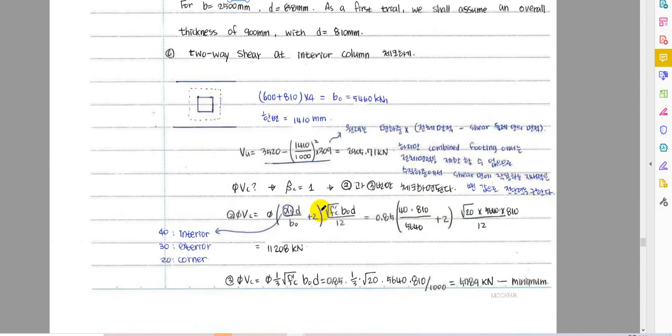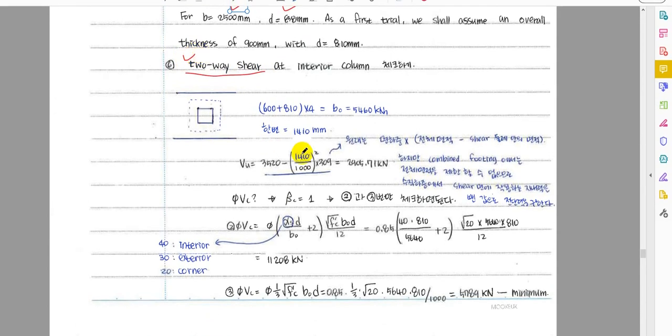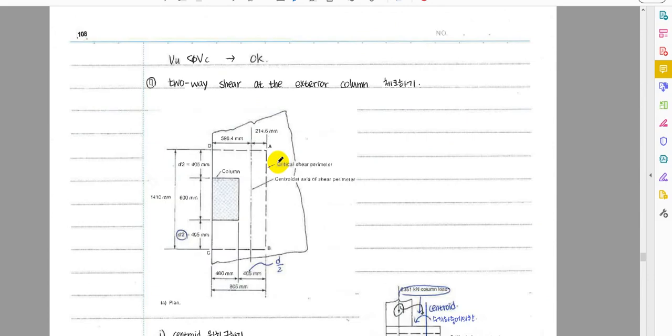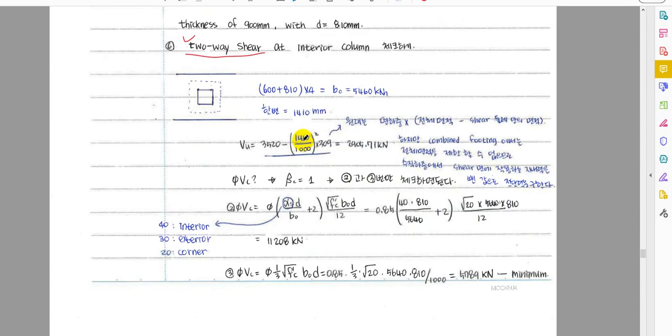And here we have the same thing as for the foundations. We have two-way shear situations and one-way shear situations. The two-way shear situations are exactly identical to what we saw for the foundations. We calculate the shear force on the effective area outside of the critical section, the so-called punching area.